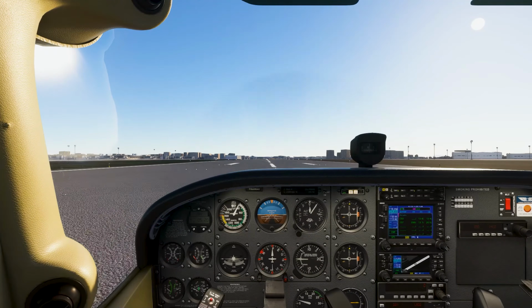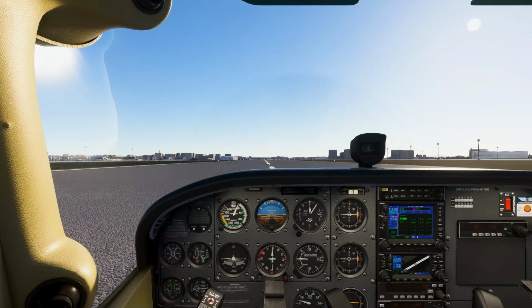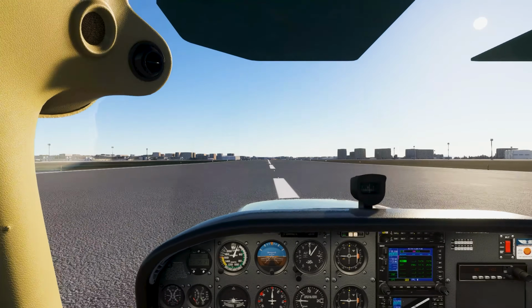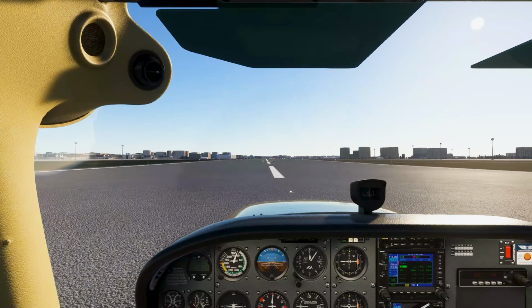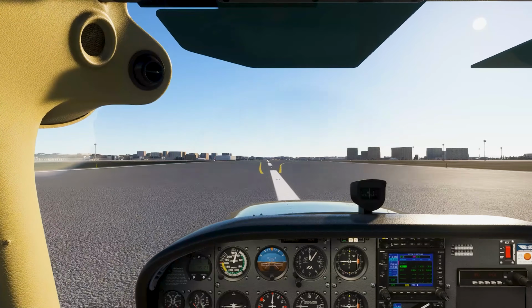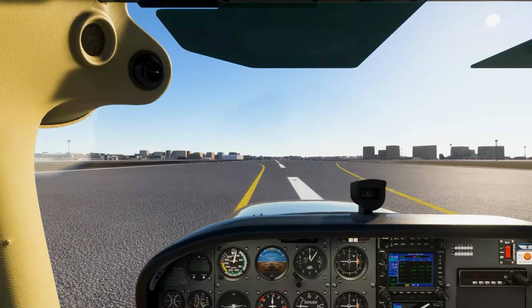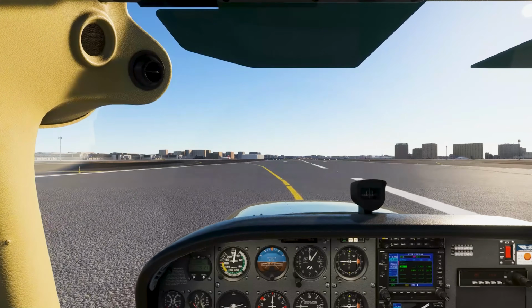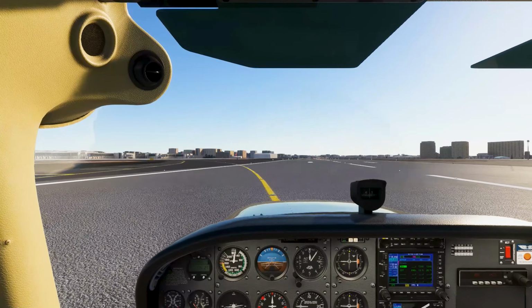Radar contact lost. If ATC loses radar contact with your aircraft for any reason, they may ask you to ident when re-establishing contact to confirm they have the correct aircraft. Traffic advisory. In busy airspace or when nearby traffic may pose a conflict, ATC might ask you to ident to ensure they are providing accurate traffic advisories to you and other aircraft in the area. After changing transponder code, ATC may request an ident to verify your identity after you change your squawk code.